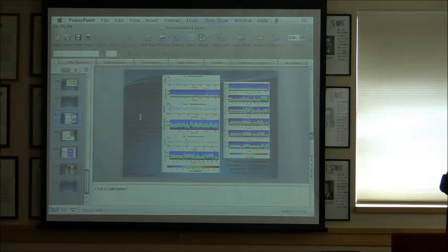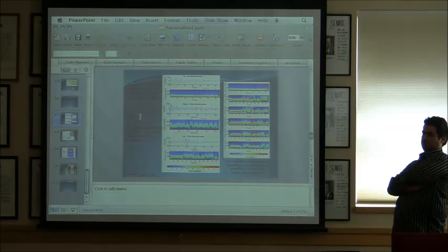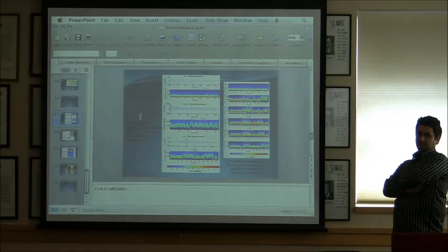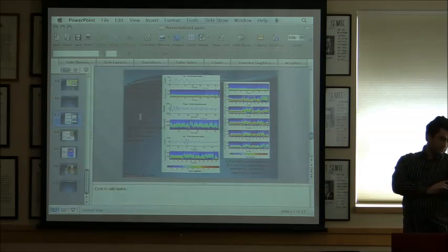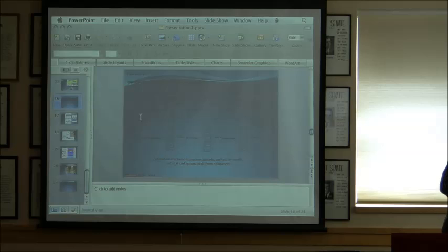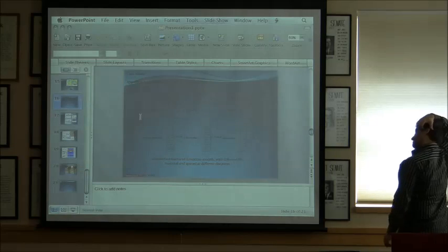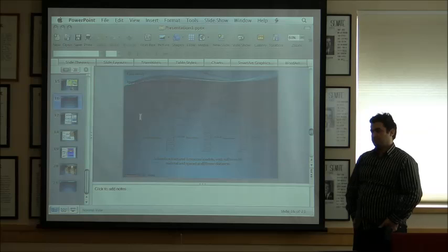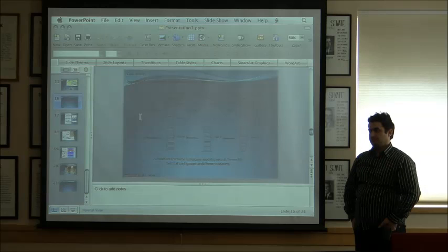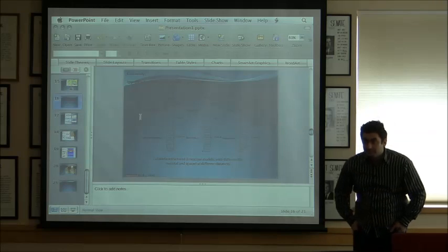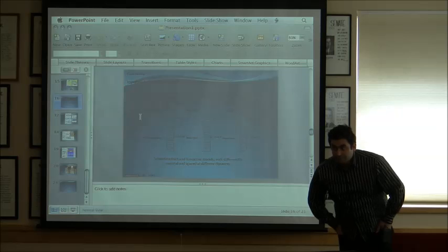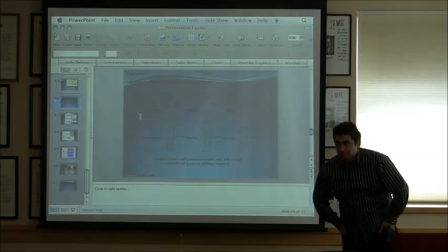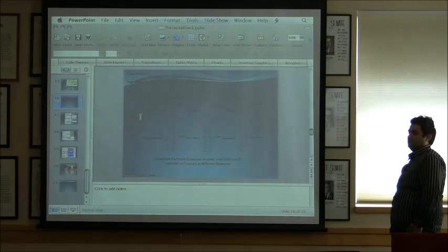And that partially is going to be due to crack size, signal frequency and crack fill and all this sort of stuff. So it seems to work well when the cracks are filled with water and there's a huge attenuation of the signal. But I haven't seen anybody really look at, as you get back to just that first case where it's air on air and just crack density, making that same argument with a much more narrow frequency loss.